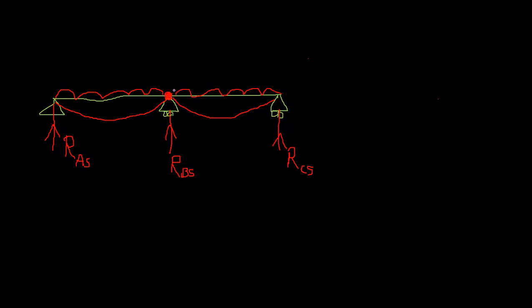So we are working under the force method. We deal with the bending moment, so the corresponding displacement is the rotation. At the end, we work with the compatibility shape of the structure using the force method, and we solve for the unknown forces. I take the clockwise moment as positive.